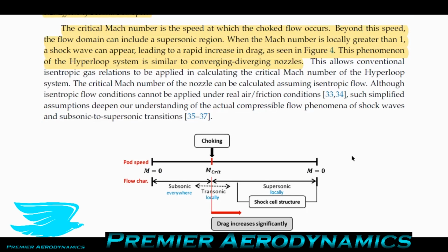So that means that when you put flow through it, it then reduces in cross-sectional area and the flow has to accelerate. At the point of the smallest cross-sectional area, ideally the flow will be at the speed of sound. Then when you diverge the nozzle, the flow will accelerate past the speed of sound. That's in theory.